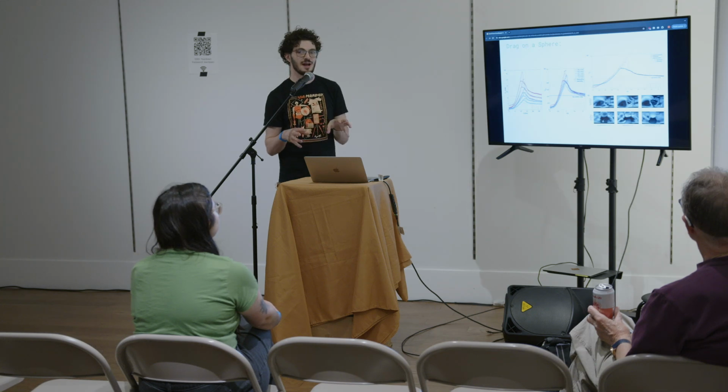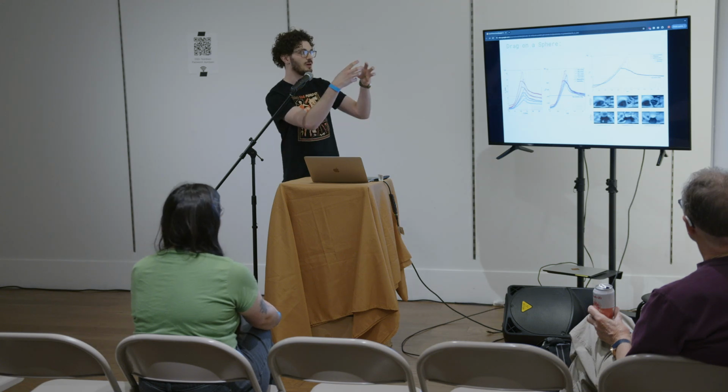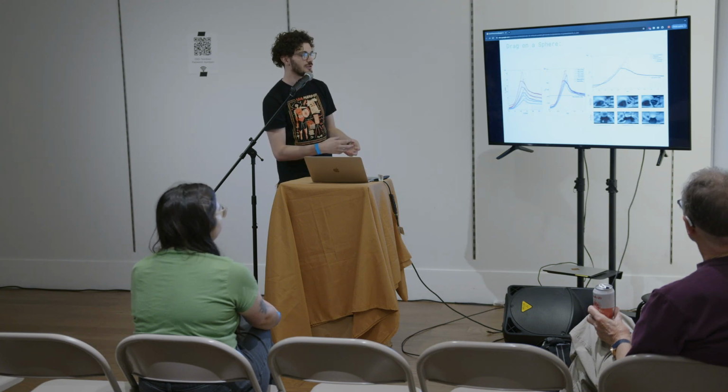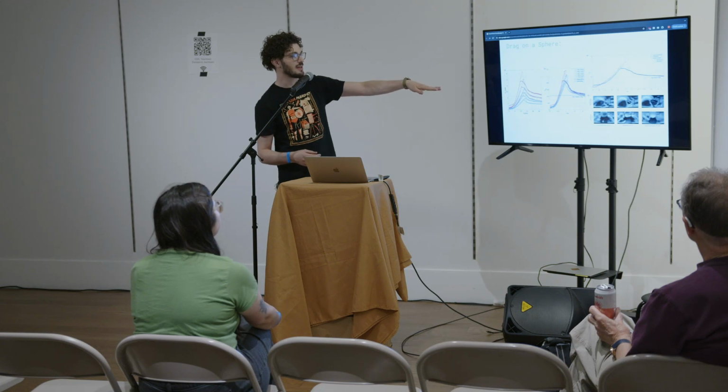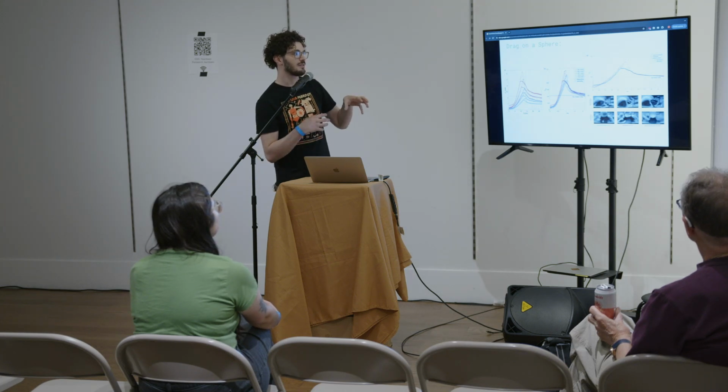The free stream drag of a sphere is something that's well known in literature, has been for a long time. What that means is if I take my sphere and put it all the way into the water, so it's fully submerged, it should have a certain amount of drag. And that's characterized by this 0.4 value for the drag coefficient. This shows over a bunch of different flow rates that all of these experiments approach the same free stream, fully submerged drag.